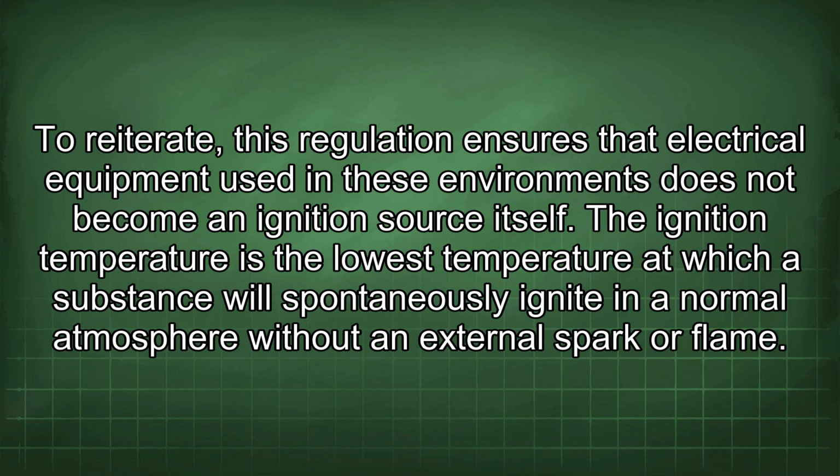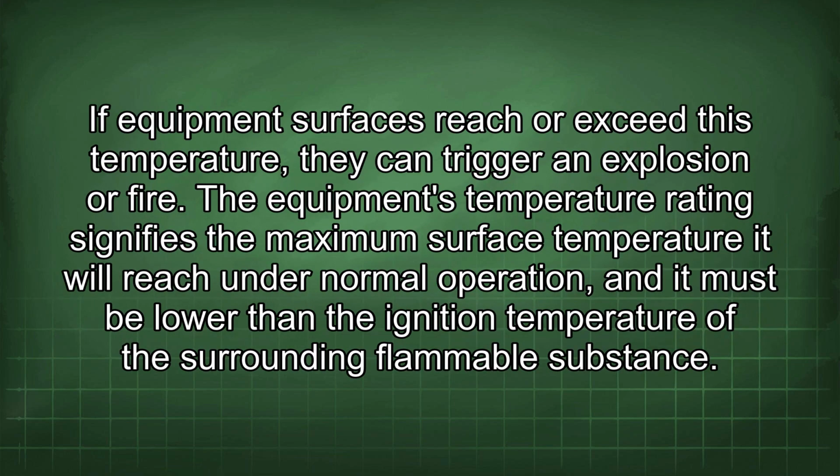The ignition temperature is the lowest temperature at which a substance will spontaneously ignite in a normal atmosphere without an external spark or flame. If equipment surfaces reach or exceed this temperature, they can trigger an explosion or fire. The equipment's temperature rating signifies the maximum surface temperature it will reach under normal operation, and it must be lower than the ignition temperature of the surrounding flammable substance.